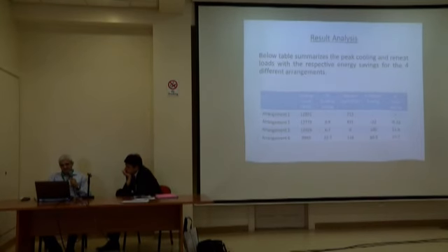The results for these configurations are summarized in the table below, where arrangement 1 is the standard arrangement, where you need about 12,891 kilowatt of cooling and 713 kilowatt of reheating. The reheat can be done through electric, water, or other means. Arrangement 2 is the one where we had a bypass coil. It turned out not to be effective, since some of the latent heat is being bypassed through the coil, and also we needed more energy to reheat. So the second arrangement was not efficient at all.